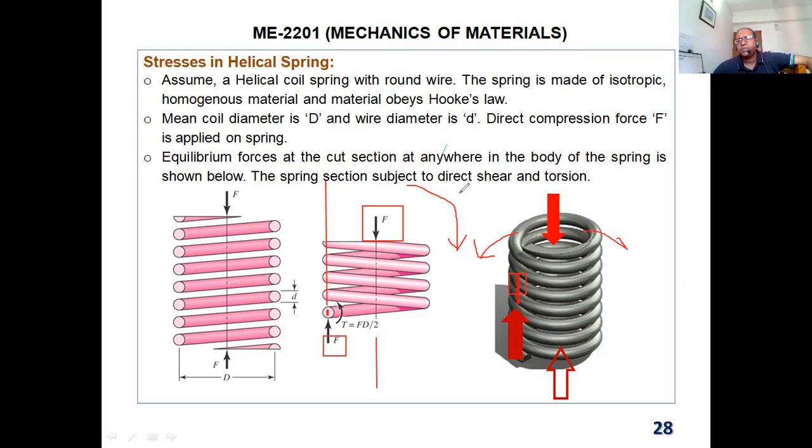For a bending moment, it would bend in some way, but in a spring, as we discussed earlier, you never see the spring wire bent like that. You see directly a failure, where the spring wire becomes two parts.